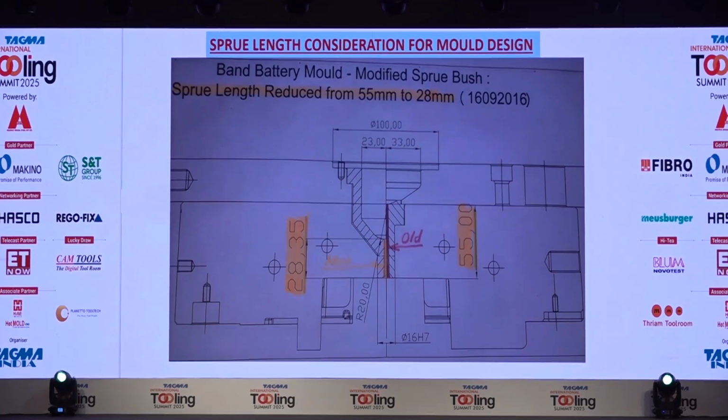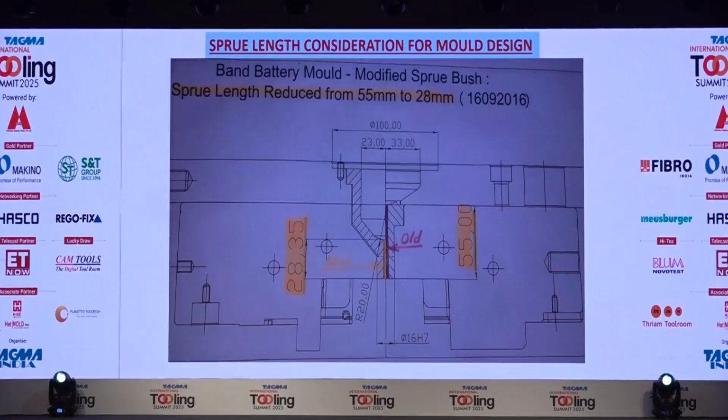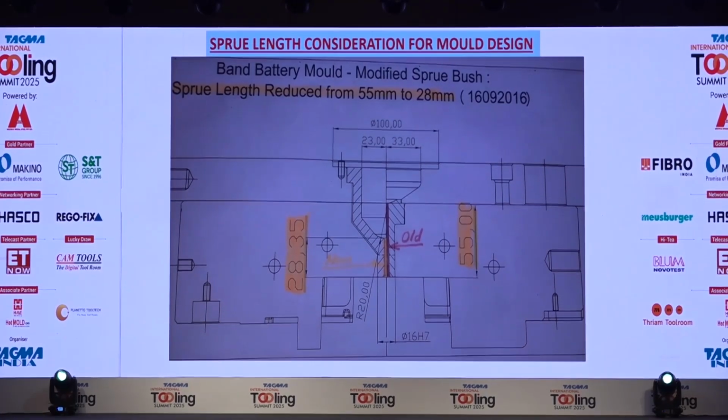This is taken out as a case study. I made it in 2016, when I was visiting a well-known customer in Pune. On the right side is the old design, where the length of the runner, the sprue, is 55 millimeter. Sprues are waste, so they have to be made to the minimum height possible so that you can limit the cold sprue wastage.